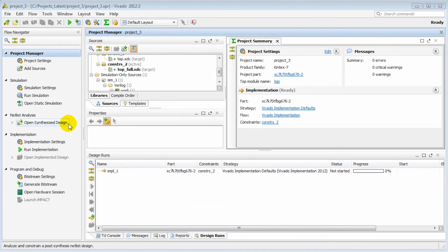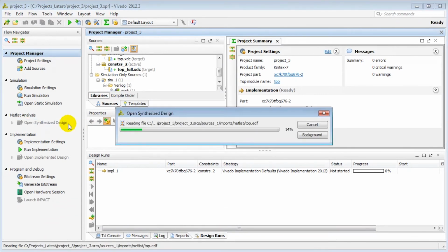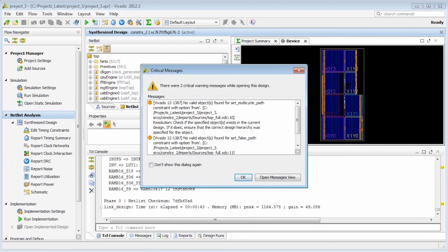Sometimes when you load a design with XDC constraint files, there may be invalid constraints. This is a possibility especially when assembling a large design with pieces from many different sources, with different timing constraints. The constraints may be invalid because the target objects cannot be found in the design. In a large design with many levels of hierarchy, an XDC constraint may attempt to target a cell or a net with an incomplete or incorrect hierarchical path. Sometimes the constraints may simply have invalid syntax. In any case, invalid constraints trigger critical warnings that you must diagnose.